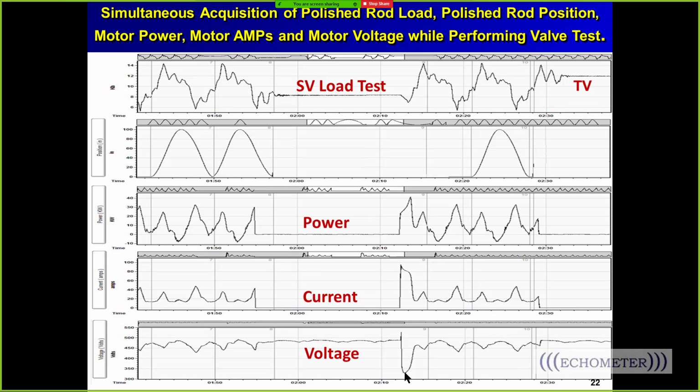You're trying to flow that energy from the transformer to the pumping unit, and that's the voltage loss, which represents the change in voltage over the wire from the transformer to the pumping unit. And the bigger the wire, the less voltage drop you're going to have. That's really the idea I wanted to talk about, but the equations are discussed in that paper.